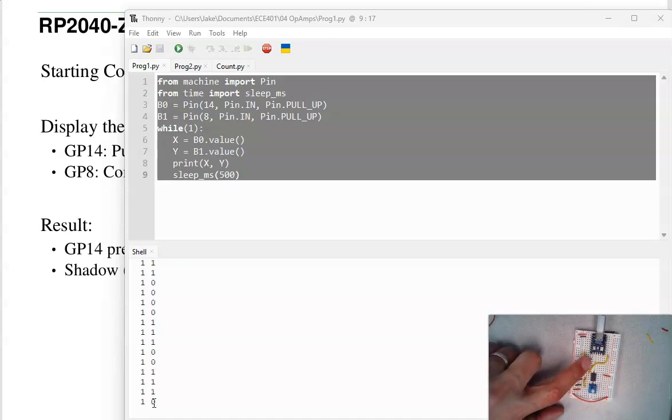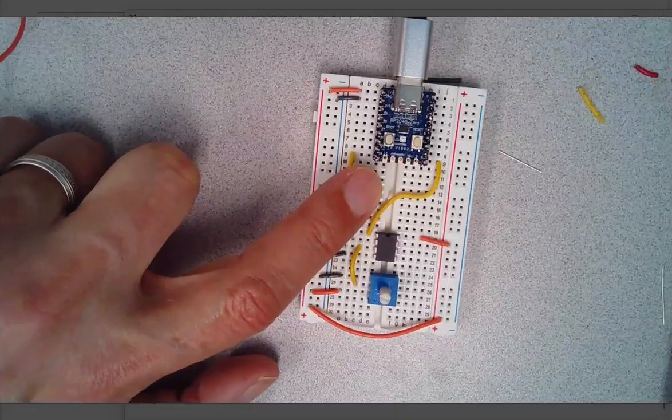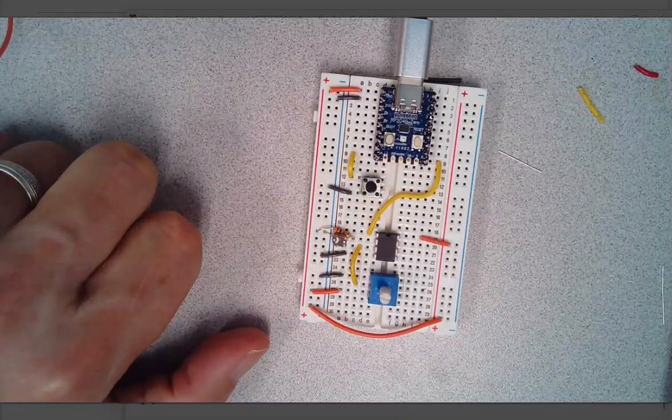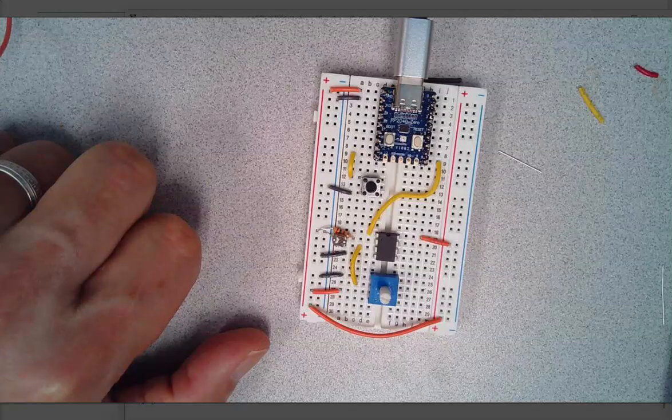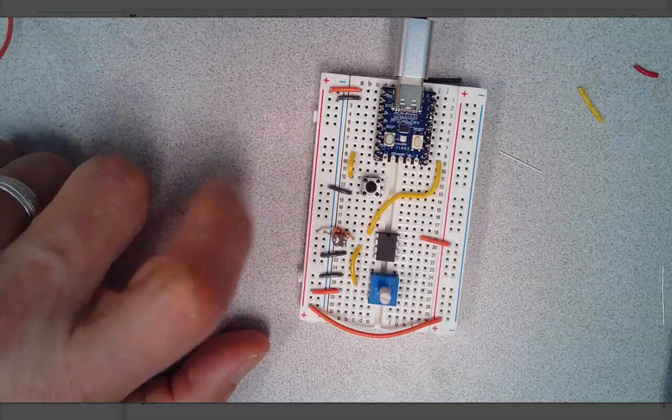And the other one's a push button. When I hit the button, I get logic 0, logic 1. What the push button does is it just has this pin tied to ground through the push button. To push the button, these are shorted to ground. Open, it's not connected.